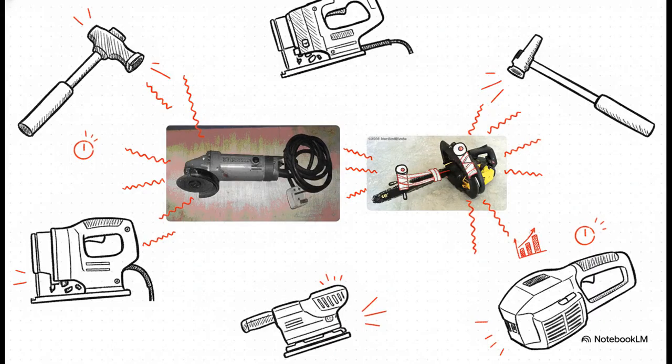And when we look at the specific equipment being used, we see the usual suspects. Tools like grinders, sanders, jigsaws, chipping hammers, and chainsaws consistently rank as incredibly high vibration equipment. When conducting these hand tool measurements, sensors are often literally taped or wired directly onto the handles to capture that crucial AHV data accurately while the tool is cutting or grinding. These specific tools, if they're used continuously, will eat up a worker's daily exposure budget incredibly fast, hitting that 2.5 EAV action limit way quicker than you might assume.